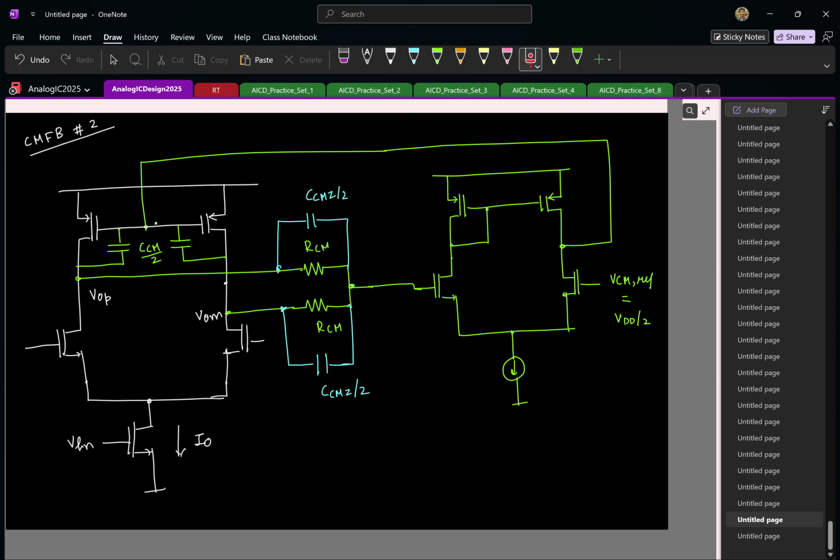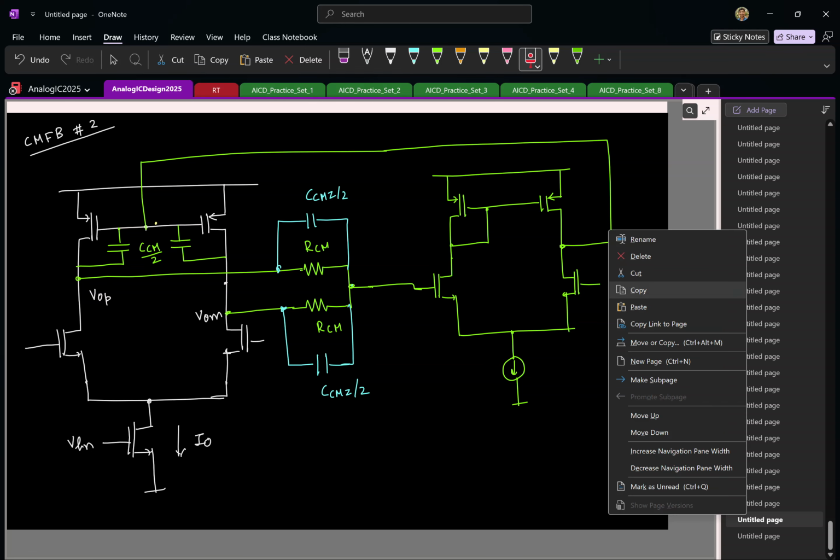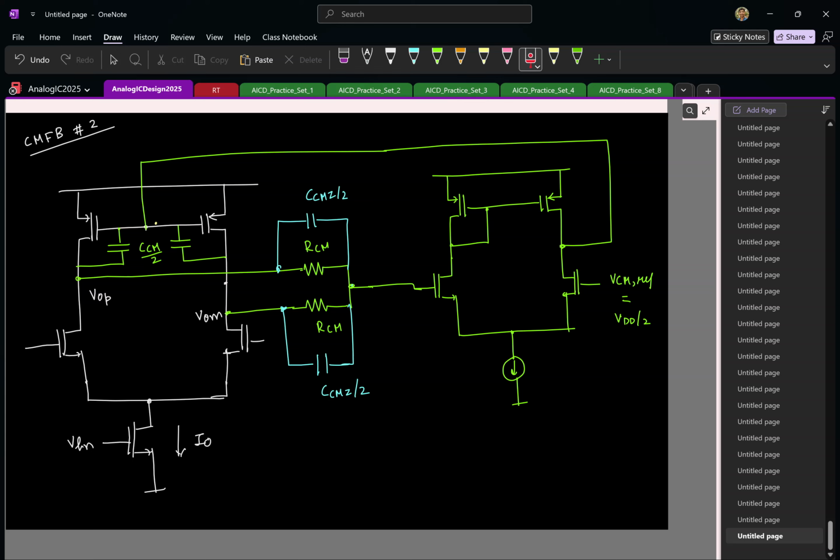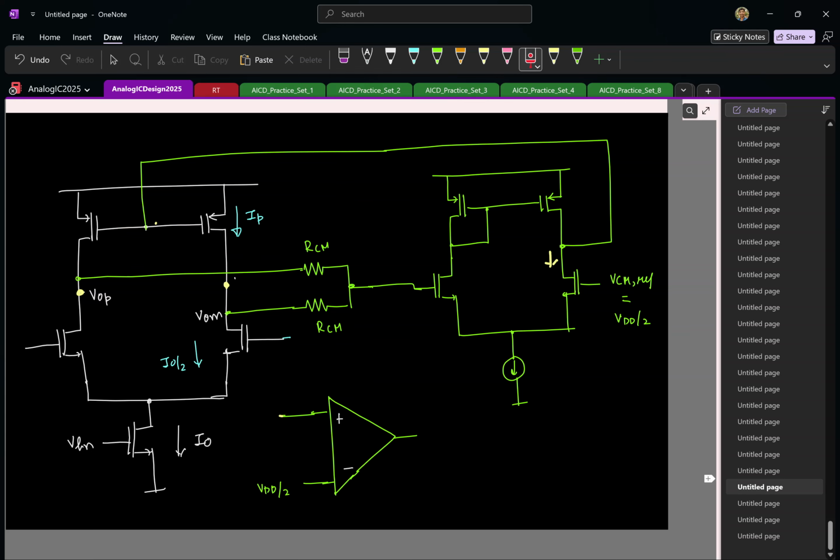Great. So one last thing. Let me copy paste this. See here, when we looked at the CMFB, we started off with the goal of having an Opamp, right? This Opamp is what we realized as this fellow. Now, the simplest realization was the 5 transistor OTA. How many different variants are there for the 5T OTA? Is this the only way to make the 5 transistor OTA, or can I have different circuit implementations?